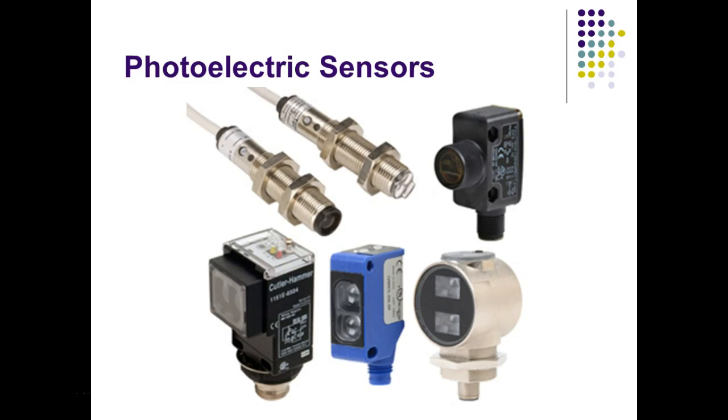So these are our photoelectric sensors, and we've got a ton of these on our line over there. Photoelectric means they generate light and sense light. Sometimes they're at a wavelength we can't see, but all the ones we have over here are around 660 nanometers, so it's red. Most of ours are red over there.